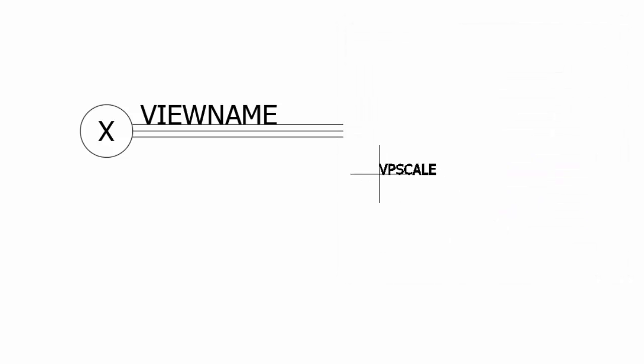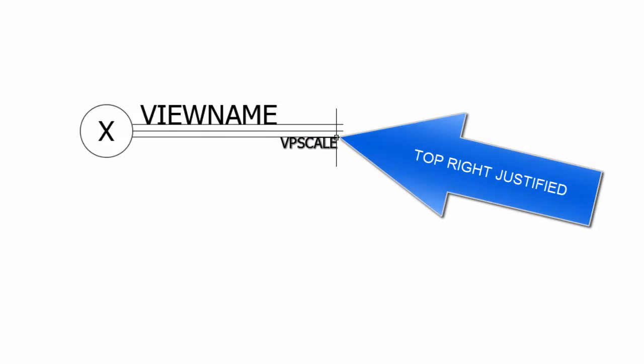and let's pick OK. Now top right, again nearest O-snap, top right, once I pick this, you're going to see the text move. What that means is that because it's right justified, the text will grow in this direction, which is what I want. I don't want my wording to go out past the line. Now that I'm done with my lettering guides, I'm going to delete them.